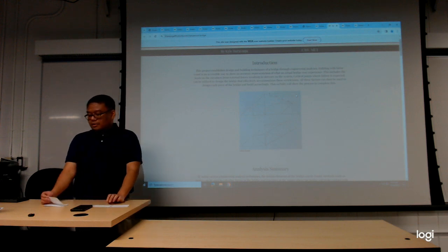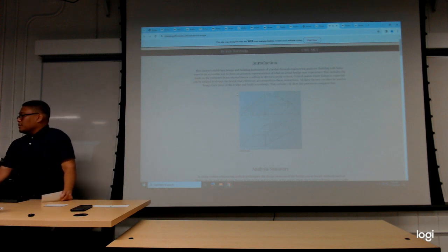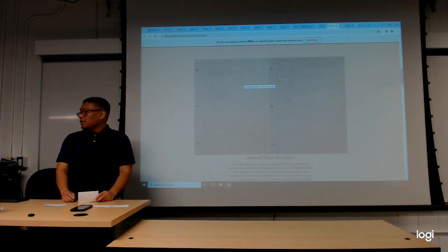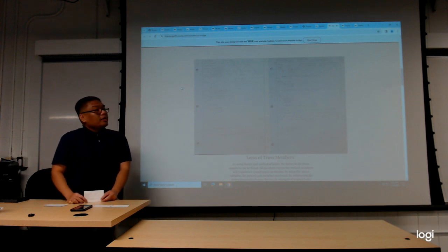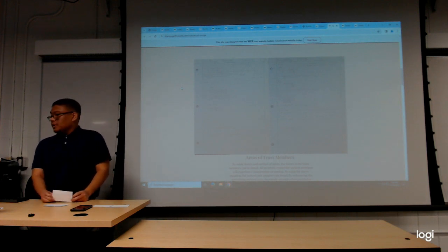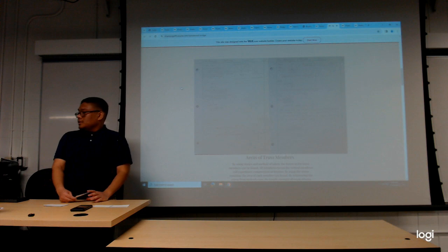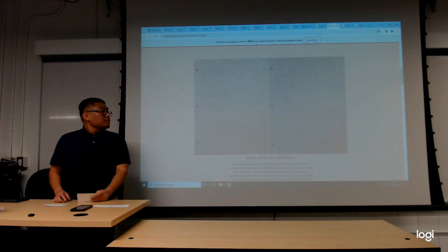The types of engineering involved in this project are mainly statics and mechanics of materials. Looking at a good example of this in one of my analyses, in this analysis, I find the area of the truss members. After creating a free body diagram, some of the forces and some of the moments can be used to find the reactions at the ends, where they will contact the abutments. In this analysis, particularly one thing to consider is, since it is only half of the bridge, the applied force is half.